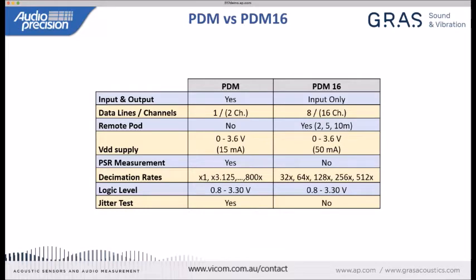For our regular PDM module, there is a line driver accessory, but it makes up for or masks the issues of cable loading, but you do tend to get into some issues with reflections and ringing due to impedance mismatches. So a couple different schemes, but probably the largest issue is just the raw number of input channels you want to measure.